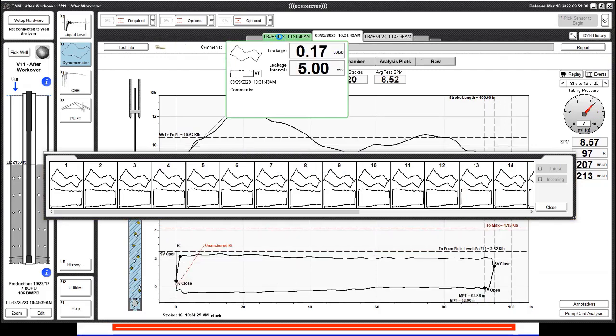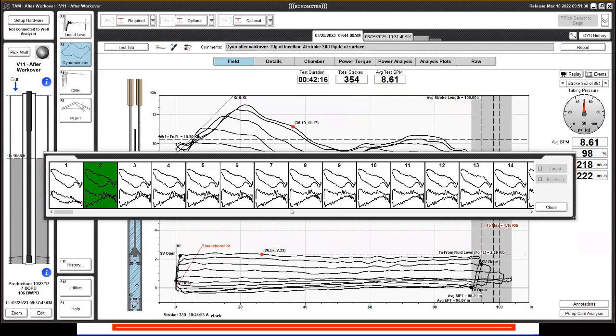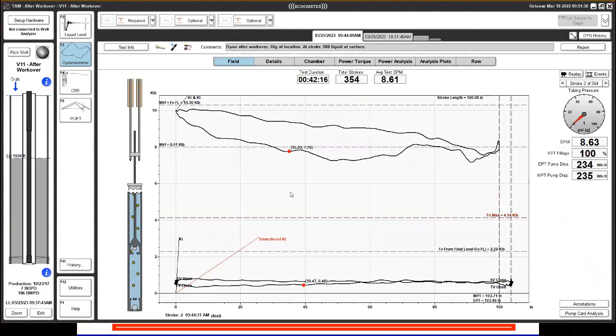I don't have a handy example of the hole in tubing, but I have an example of a partially empty tubing, which is a well that was measured right after workover. We can see how, when we start recording, we have a flat dyno card. We have a flat dyno card that is not resting on the zero load line, which means it's not a deep parted rod. That flat line is not below the zero load line, so it's not a shallow parted rod.